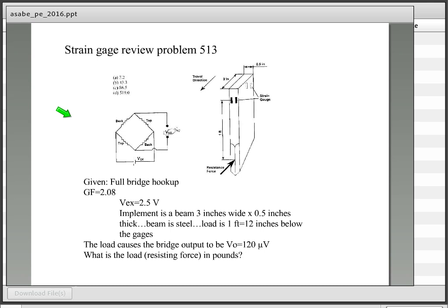If you had a load on a part and you wanted to actually measure it rather than calculate it, we typically would use strain gauges. That would be into the area of what we would call experimental stress analysis. And so you want to be a bit familiar with strain gauges.